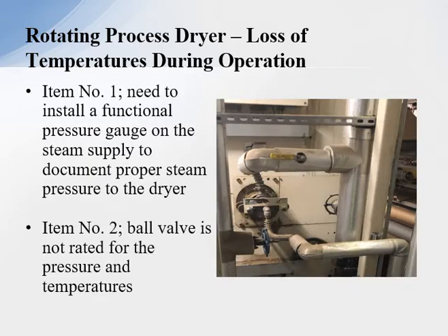One of the items that came to our attention immediately was there needs to be a pressure gauge at the inlet of this process here. There was a question exactly what pressure is after the control valves. The steam pressure is coming through isolation valve, strainer, and a control valve. Therefore, we really need to know what pressure is coming into this process unit right here.